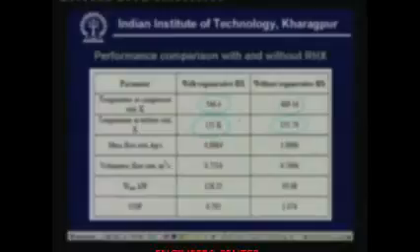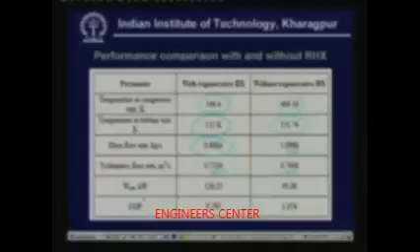Exchanger. This is 131 versus 151. As a result of this, your refrigeration effect increases. Since refrigeration effect increases, required mass flow rate reduces when you are using a regenerative heat exchanger. That is what you can see. And the required volumetric flow rate also reduces. That means basically you will be handling less amount of air.